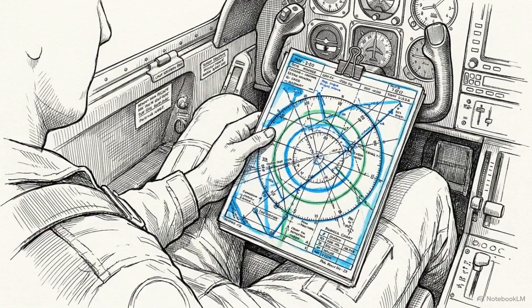By combining the physics of radio waves with geometric vector limits, an aviator constructs a definitive three-dimensional navigational picture. This top-down approach chart shows the VOR component's spatial function, providing a precise lineal radial projecting straight outward from the ground station. The complementary DME component converts the UHF pulses into a rigid circular position line. The exact mathematical intersection of this lineal radial and circular arc generates an immediate absolute spatial fix for the aircraft.